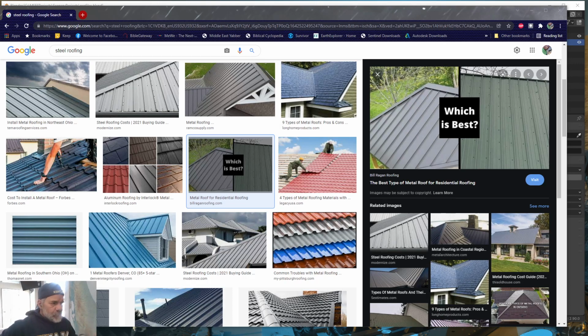So steel roof or steel siding comes in many different styles. Okay, the basic two types of steel roof is you have a standing seam, which means that it's smooth between the ribs, plus there's no visible fasteners to the roof. The ribs, and I'm giving you imperial dimensions, so you guys can convert it to metric. I normally use metric a lot, but anyway, you can convert. The distance between the ribs is either 12 inches, 1 foot, or it's 1.5 feet, depending on the style that you're trying to make.